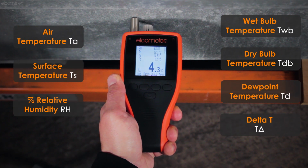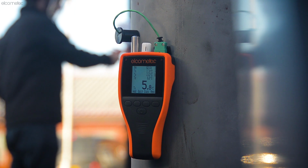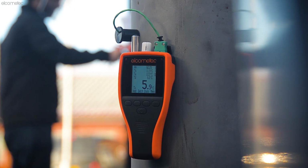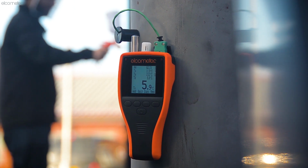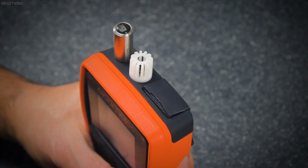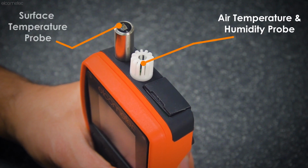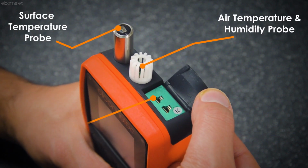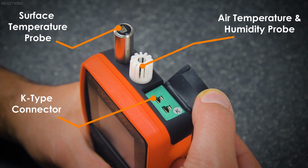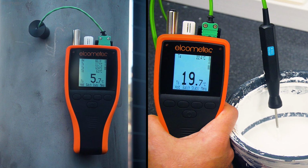climatic parameters simultaneously, telling you if conditions are suitable for painting. What's more, it can continuously monitor and log the conditions as you paint, and instantly alarm if one of the parameters falls outside of the specified range. Equipped with an air temperature and humidity probe, a surface temperature probe, and a K-type connector, which allows you to connect additional external probes such as magnetic surface temperature probes or liquid temperature probes.